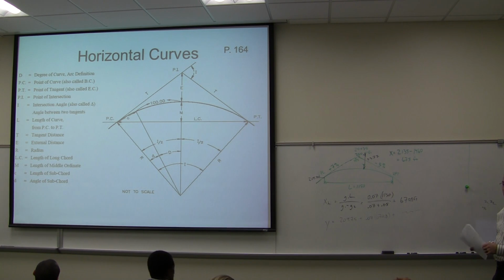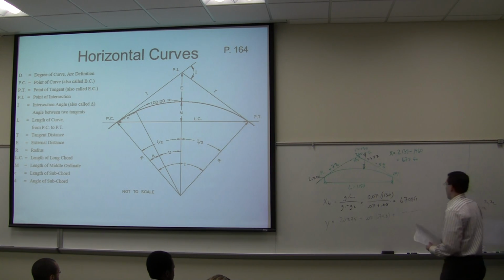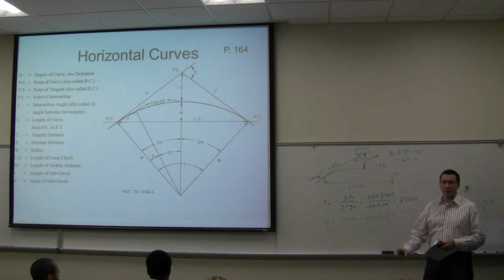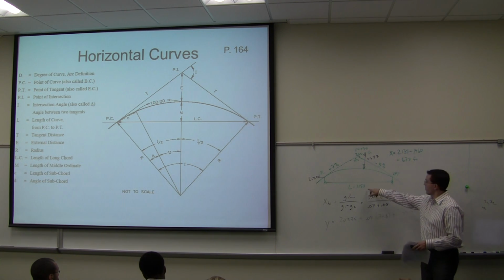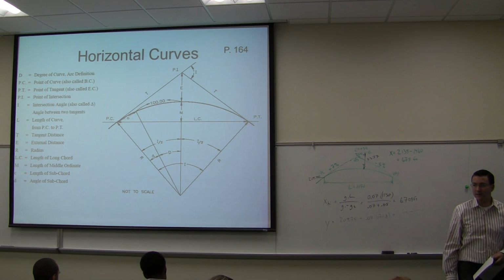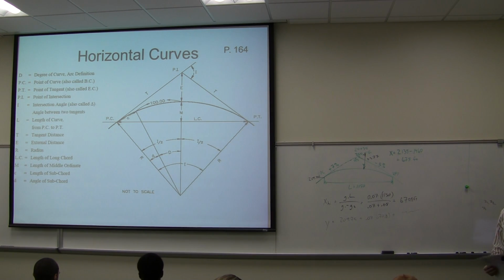I just got the same exact answer as our y elevation earlier. Finishing out that equation with 670.8 in there instead of 675? Yeah, I don't know how that happened. Wow, I got pretty close. It's not exact, but on a curve of 1,150 feet, we're only looking at a 4-foot difference, so you're looking at very minimal difference.